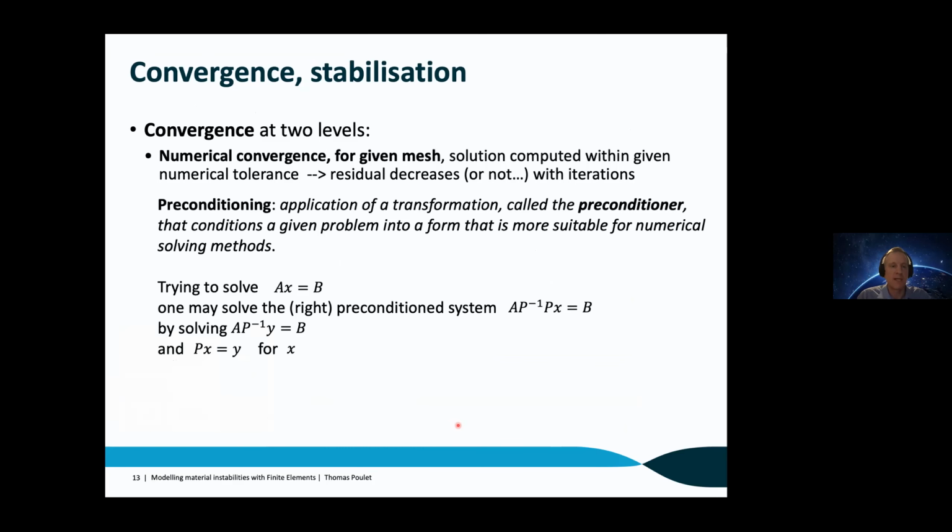And in that respect, you need to be aware of the word preconditioning. This is an important aspect of it, which is one of those mathematical tricks being used to solve your problem. As I said, you have this big vector of unknowns. This is my vector X, which contains all my degrees of freedom. So if my mesh has 1 million points, and I'm solving, let's say, for temperature and for pressure, I might have 2 million degrees of freedom. So it's one big vector.